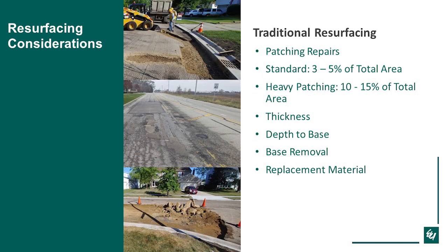Patching repairs, I would say standard is usually throw on 3 to 5% just in case you run into some issues after you mill the surface. But if you think based on the pavement management software recommendations and information that you might have additional base repair, then you might want to throw a heavier amount of patching at your 10 to 15%.